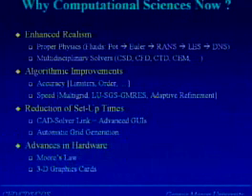So why would we use computational sciences like CFD now? Well, we've enhanced the realism. We can now solve many more equations reliably than we could before. If you think about aerodynamics, in the 60s we could solve reliably potential flow. In the 70s, Euler. In the 80s, the RANS. In the 90s, LES. And of course, the idea is to go to direct simulation of Navier-Stokes.